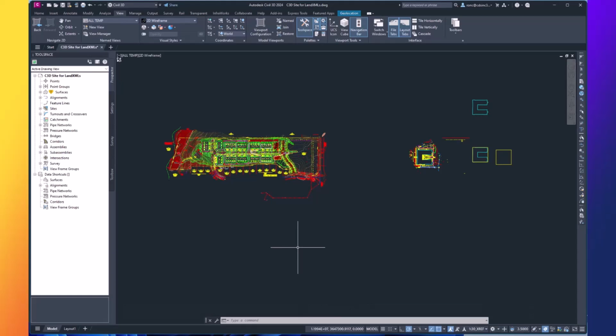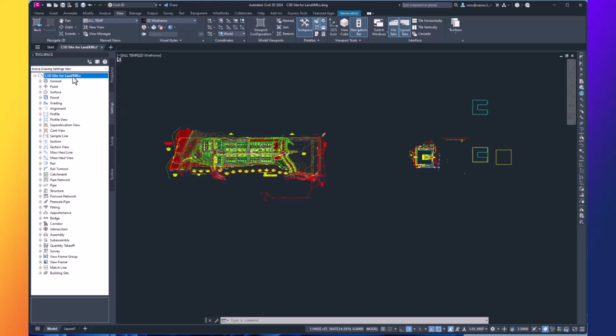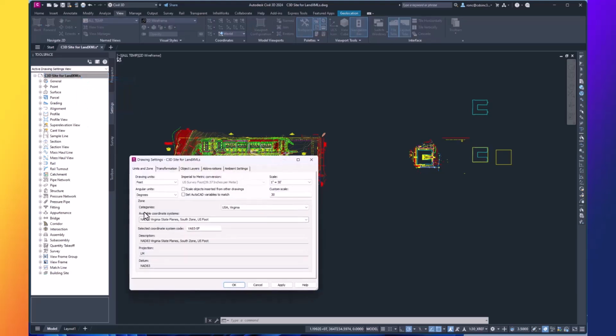Now we're looking in Civil 3D. This is the site. It's some sort of a residential plan. And when you begin this, there are some real basic settings to check on. You have this dialog over here, and it has a prospector and settings and survey and toolbox, and so forth. I recommend the very first thing you do when you open the drawing from the civil engineer is go to settings and then highlight the name of the drawing, right mouse click, edit the drawing settings.